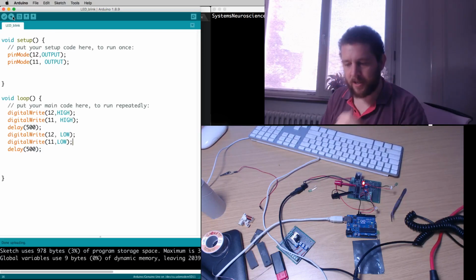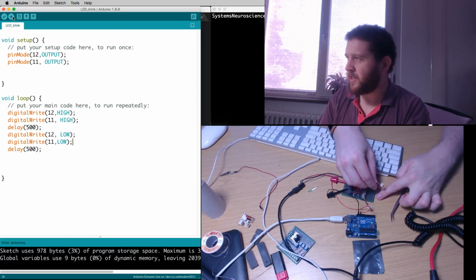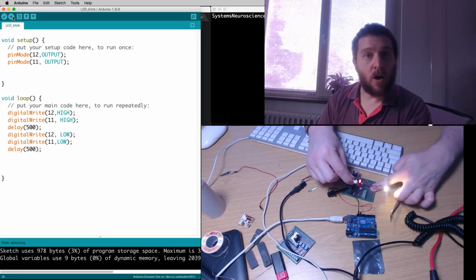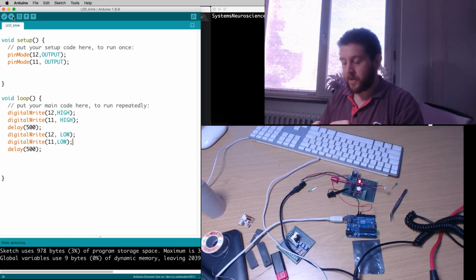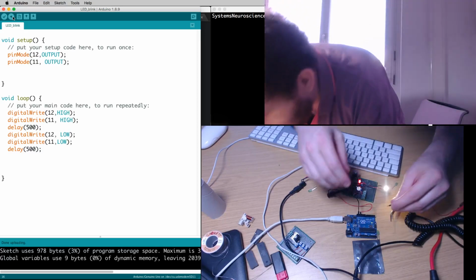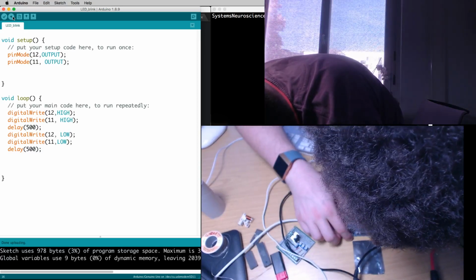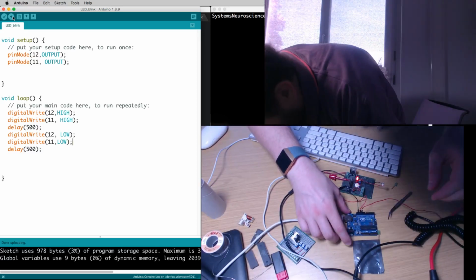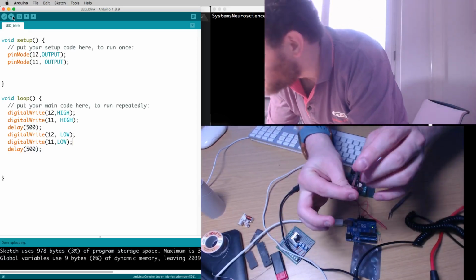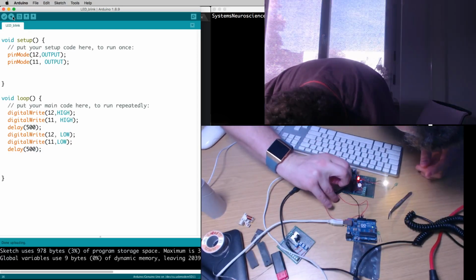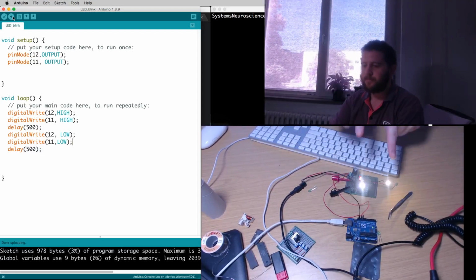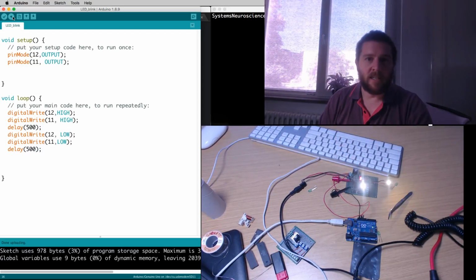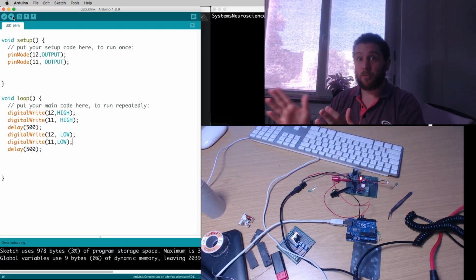You'll say, okay, so we've got one working, but the other one's not lit up. Why not? Well, we haven't attached pin 11 to our circuit. So I'll go pin 11 into the socket. Now I have to be a little bit more careful because this is quite a big bulldog clip, alligator clip, because I've got some smaller ones ordered on Amazon. We'll go bonk, like that, and here we go. We've got both LEDs lit up, and they're now addressable separately.